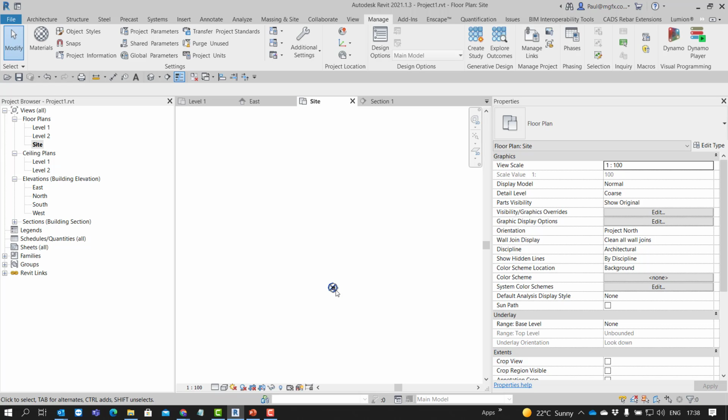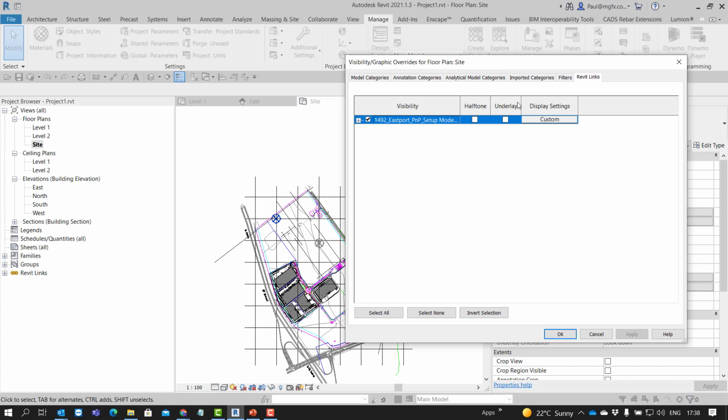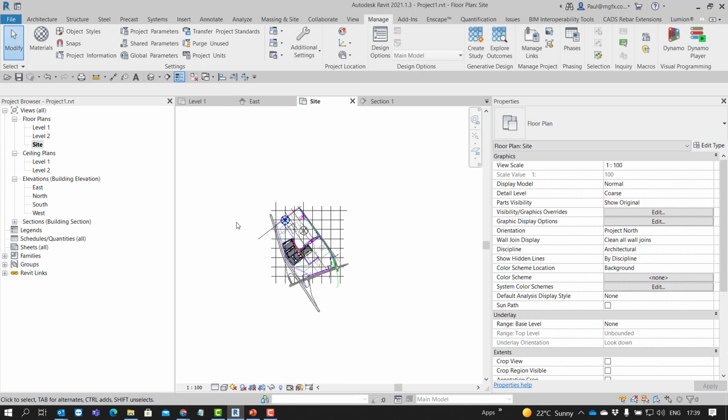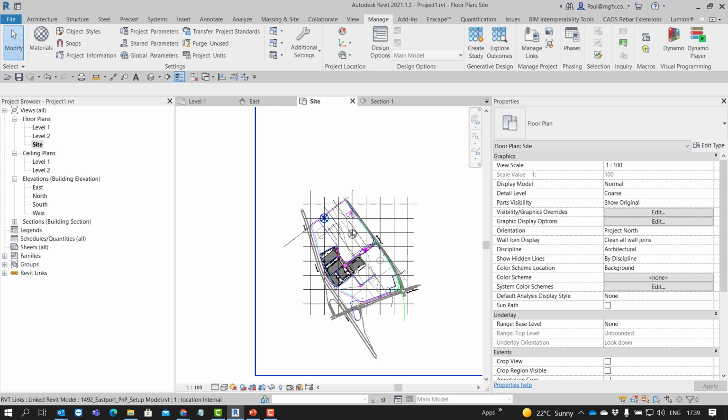If this is not possible from within the Revit LT model, I don't think you'll have the ability to override the Revit links. Then I propose that you recreate the setup file and import the CAD drawings, superimpose them on the links, and then unload the links and use that as a setup file instead. Please let us know if you need help with this process.